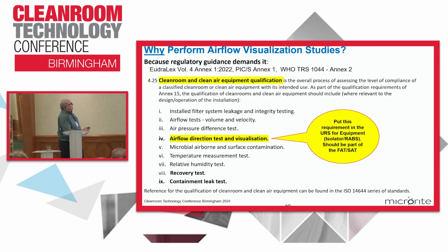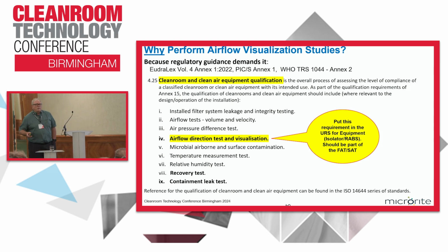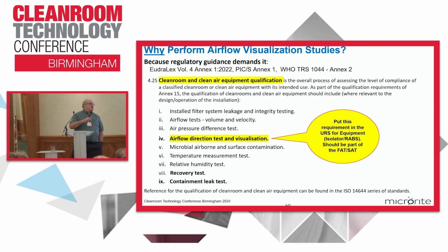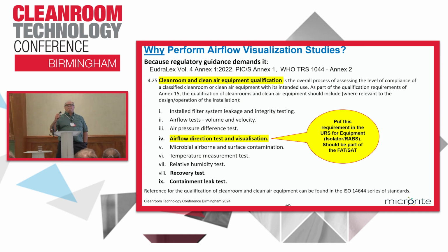Other reasons why we do the studies: Annex 1 tells us we have to do this as part of qualification. It spells out the tests that we have to do, and the test number 4 is airflow direction and visualization. Can't stress this enough on new facilities. If you're doing a new facility, or buying a new isolator or filler, make sure airflow visualization is part of your URS.